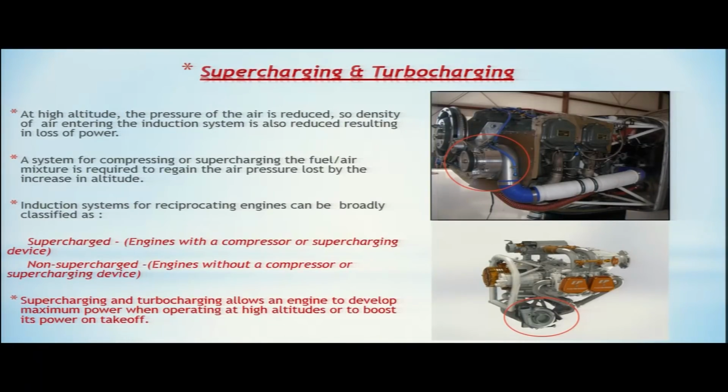Induction systems for reciprocating engines can be broadly classified as supercharged and non-supercharged. We have seen what is supercharged. Engines which can compress or supercharge the fuel air mixture to regain the pressure lost by increase in altitude are supercharged engines. Non-supercharged engines do not have this provision of compressing the fuel air mixture, so they are also called normally aspirated engines, since they are getting the normal air which is not compressed.